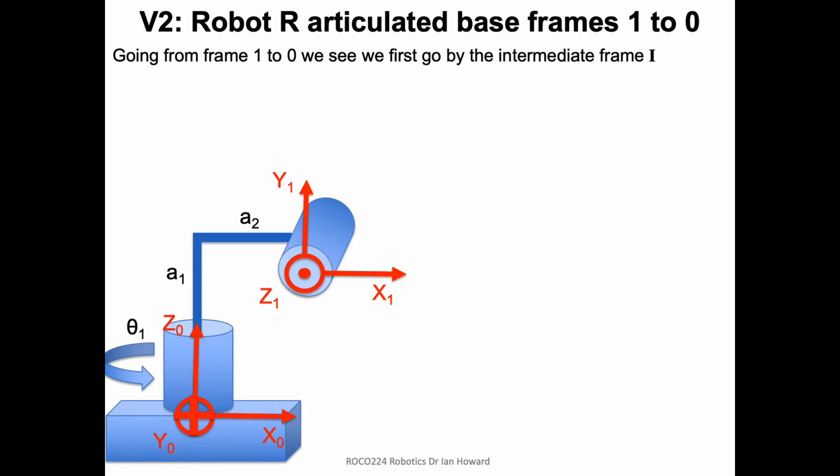We're going to put our frame at frame 1 at the next joint, which again would be carrying on with more and more links normally, and it's basically the mapping between frame 1 and 0 we're trying to get here. But now we could actually say, rather than actually do a rotation here, let's first do the shift and then we'll worry about the rotation to align the things.